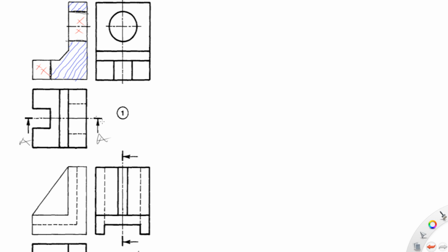So if you are to draw a sectional front view for this, what you are going to do is draw this front view, then ensure that those hidden lines are revealed, because the cutting plane is going through them. In cases where you may have some hidden objects somewhere where the cutting plane doesn't go through, you don't show it at all. You don't show it with short dashes or with any continuous line, because you are not interested in that area. That's why we are providing the section for the areas you are specifically interested in. So this one here is a full section.